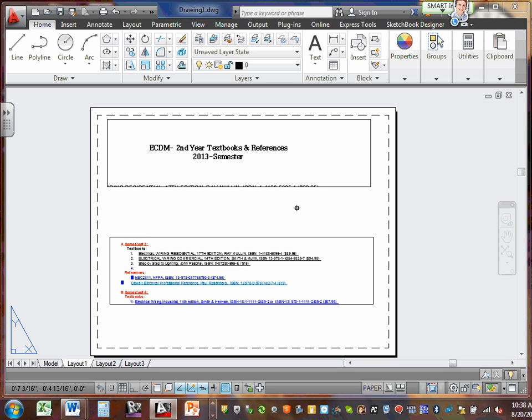Obviously when we do electrical design, we do the viewport in a certain way and we stick with it. Typically 95% of what we do is one single viewport, but you will be in a situation here with me where we're going to be using three viewports in the same drawing. The easiest way is either a new viewport, like we said, or the easier thing is to copy the existing one and adjust it to what you want. And they don't have to be the same size, guys.